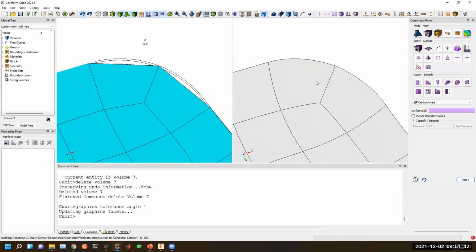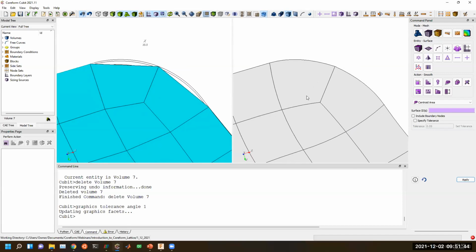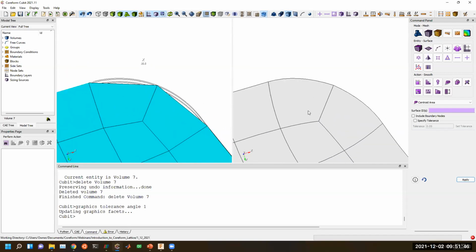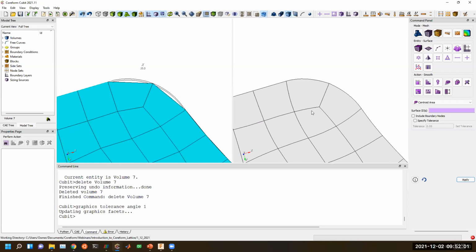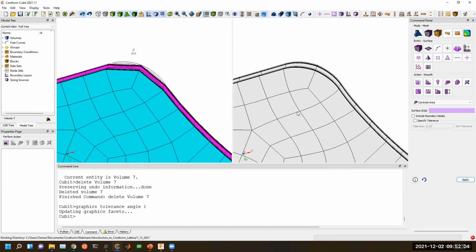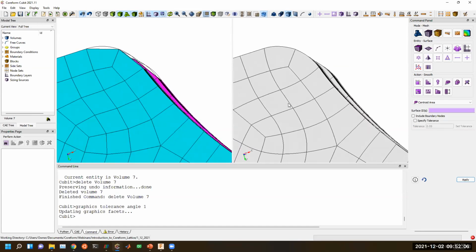Right now, we use a technique called Bezier projection with our U-splines. We aren't building rational U-splines yet. And so these are technically just an approximation to the original CAD geometry because they're polynomial as opposed to rational, for like these cylindrical faces. We are working on rational U-splines as well. But they are a better fit to that.